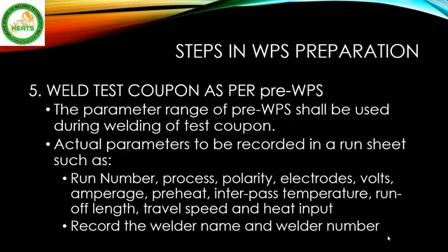Such as run number, process, polarity, electrodes, volts, amperage, preheat, interpass temperature, run-off length, travel speed, and heat input. And record the welder name and the welder number.